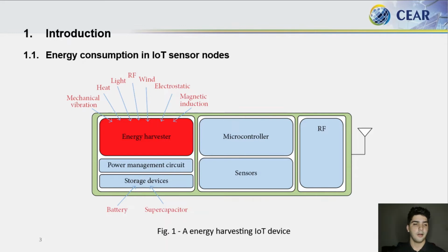In general, IoT things are powered by batteries or directly by power outlets. However, in some contexts, battery use is not suitable, for example, in natural environments, because batteries are potentially harmful. In these cases, an option for powering the sensor nodes is the use of energy harvesting. Energy harvesting is the use of techniques for collecting, power conditioning, and storage of available energy in the environment around the device that needs to be powered. For example, energy harvesting can use solar energy, thermal energy, electromagnetic energy, and others.